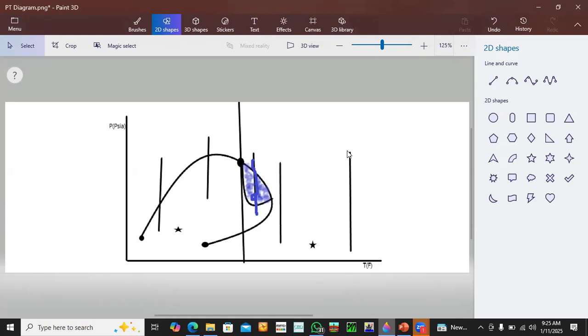So the wet gas is not typically measured with regards to the API gravity, but contains some heavier hydrocarbons ranging from C2 to C4. That's why it exhibits a bit of liquid production at the surface. It is predominantly methane with small amounts of heavy hydrocarbons, as I said earlier. It also exhibits a GOR higher than 50,000 scf per STB.